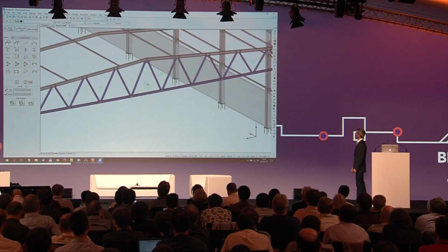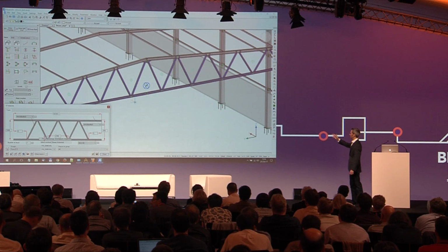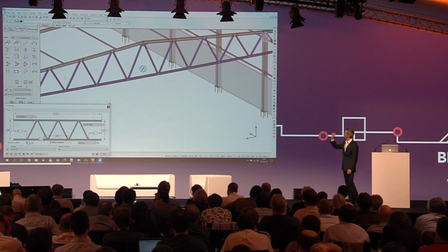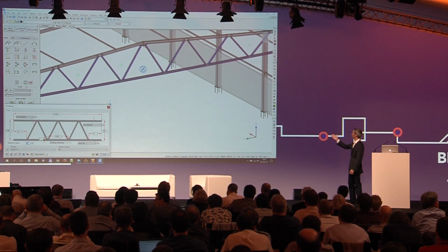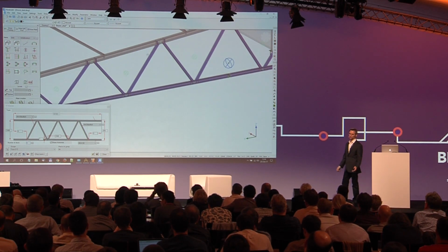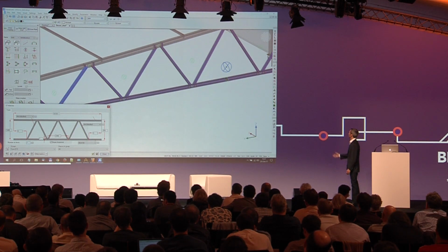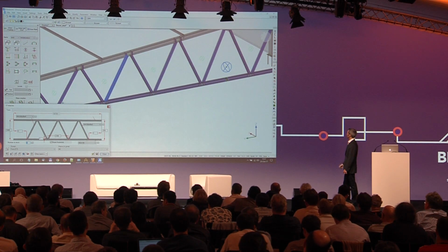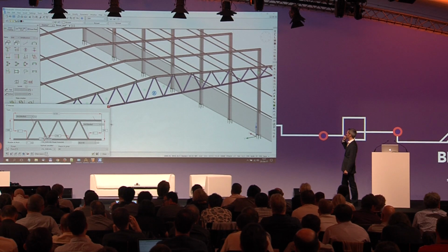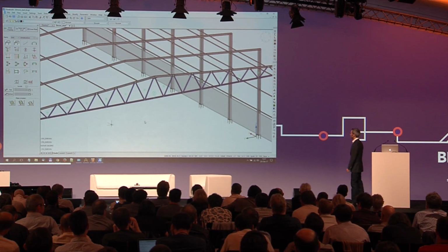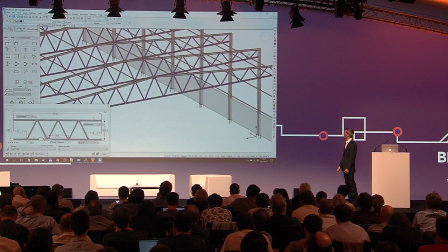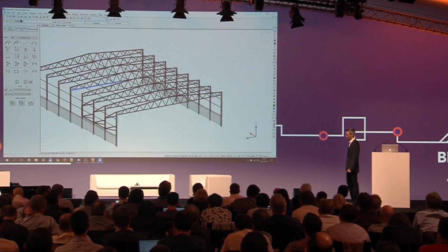So this truss is constrained using a dynamic array. And this dynamic array will keep these connections fixed when you change the number of entries. So if we reduce or increase the number of entries, these connections are relinked, some removed, some added maybe, and you can be rest assured that it stays updated. We can now, now that it's finished, also propagate this truss over the rest of the model. And all these connections, again, they follow, so they all get these new stiffeners.